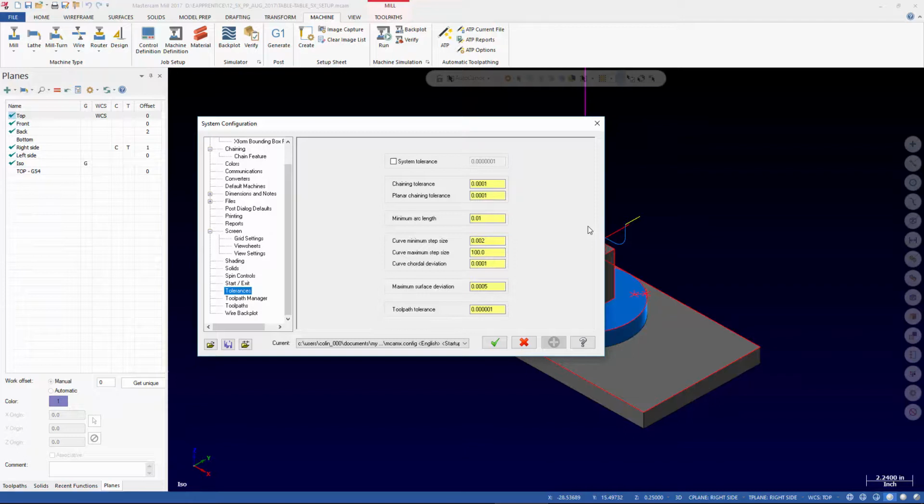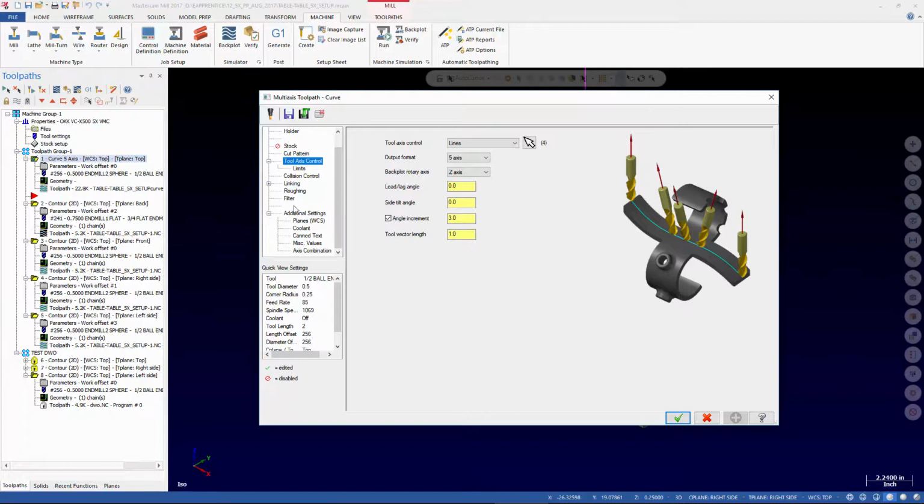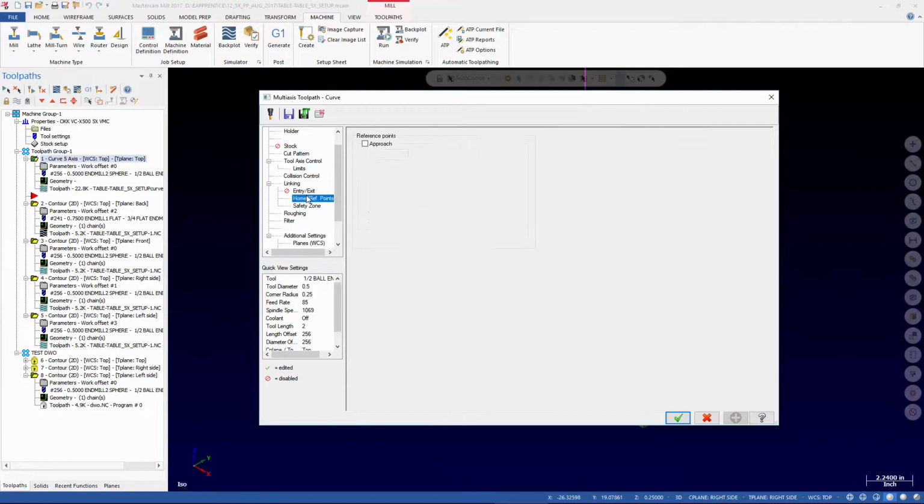So, especially for people that are just starting out, I recommend moving stuff to the system origin for 5-axis work. It'll just make your life easier, especially if you have to swap out a different machine. So sometimes you can have it where you've got a set of toolpaths for 5-axis set up, and the operation itself has, or at least had in the past, machine settings, and they may have moved those out.